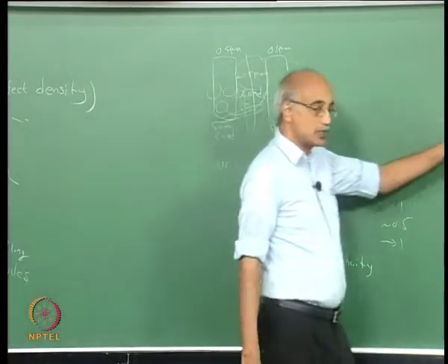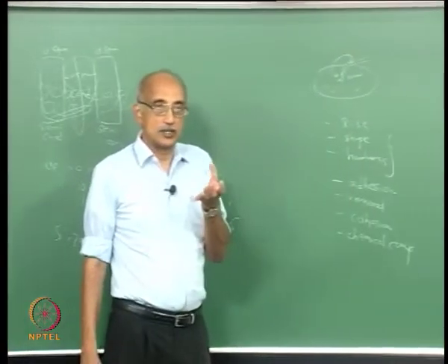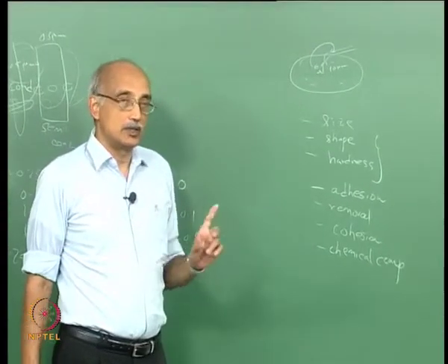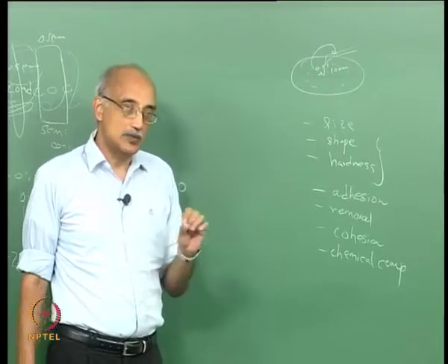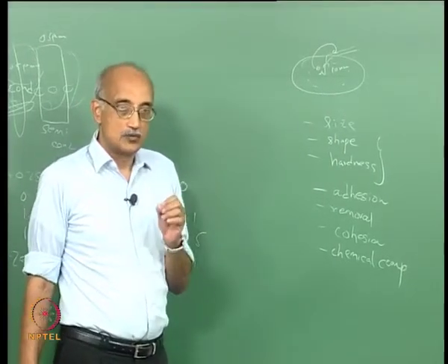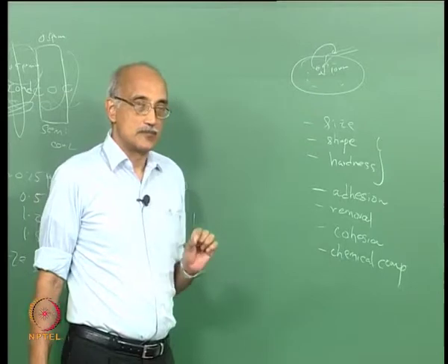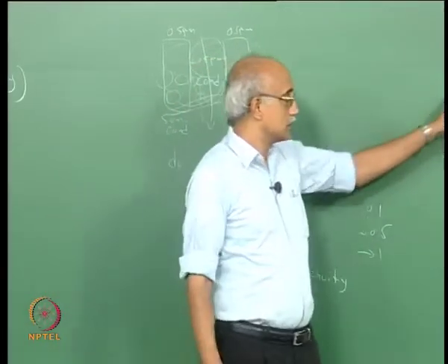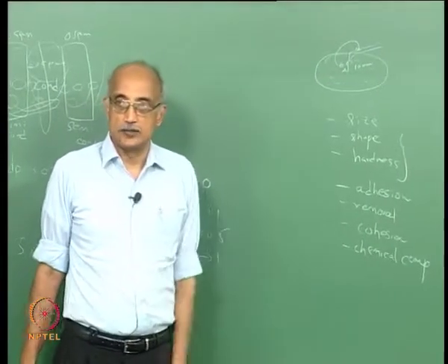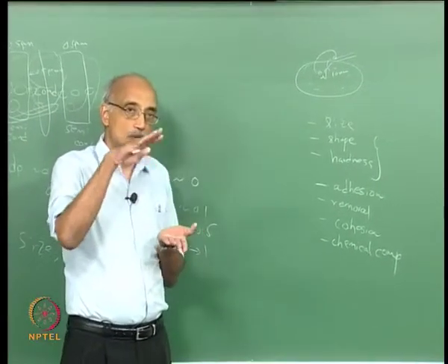Similarly, in the case of the hard drive, which is flying 10 nanometers above the disk, 1 nanometer will be taken for design purposes as a critical size, and all containment strategies will be developed for 1/10 of the critical dimension. Again, the reason for that is to build in a safety factor. If you know that 10 nanometers is going to cause a failure, you don't try to control particles below 10 nanometers.